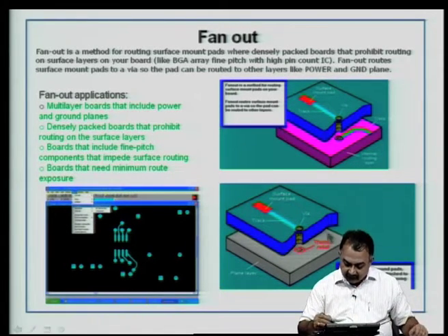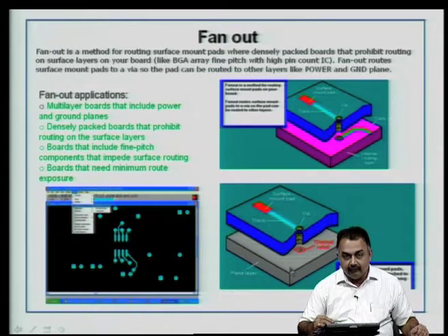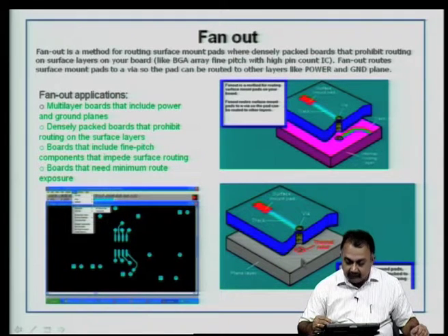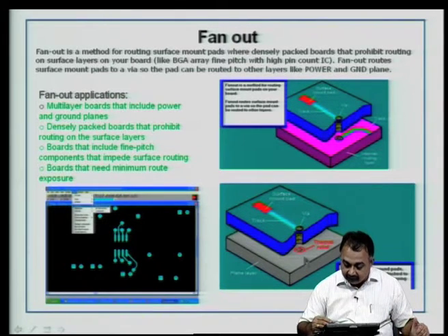So, in the second part you can see the same structure, surface mount pad, there is a track, it ends in a via, it goes through the next layer, and this is a thermal relief, there is a power plane, and there you have provided what is known as a thermal relief pad. Okay. In some cases we will use a thermal relief, which I will mention shortly. The difference between a normal pad and a thermal relief pad. Here you get a normal pad, here you are using a thermal relief pad.